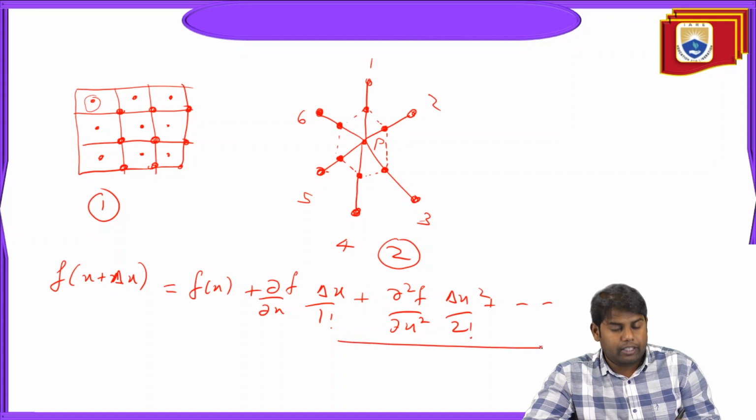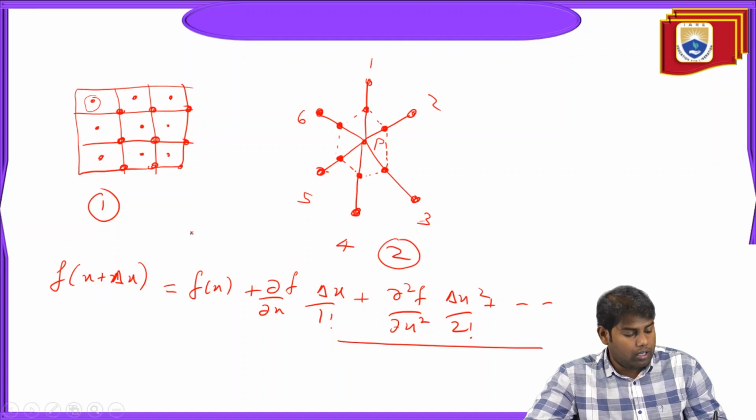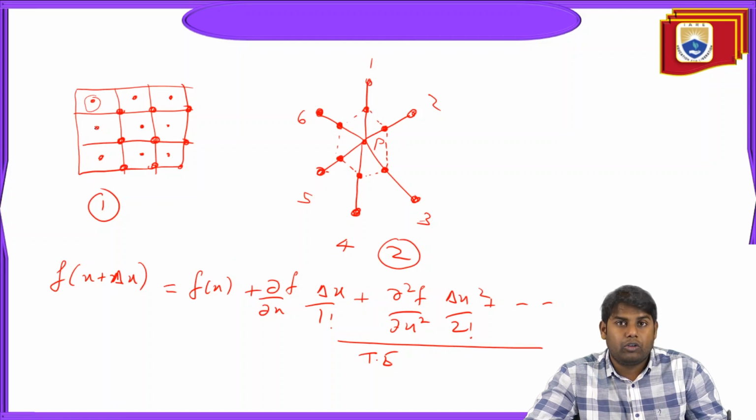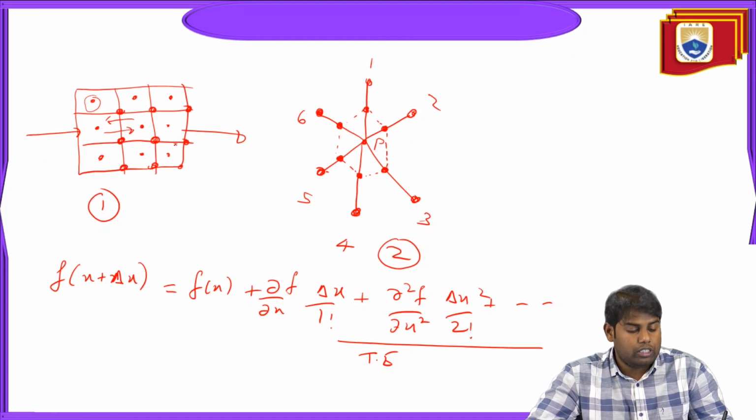So we will actually neglect some higher order terms, so truncation error terms, in the finite difference method. But for finite volume method, what we do is, we have conservativeness. Okay, so there are no truncation error terms. So whatever the flux going here, it will go here. So internal fluxes will get cancelled. So the global flux, whatever flow enters, that flow leaves. Okay, so this is the procedure we have in the finite volume method.